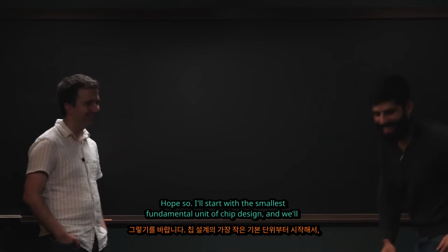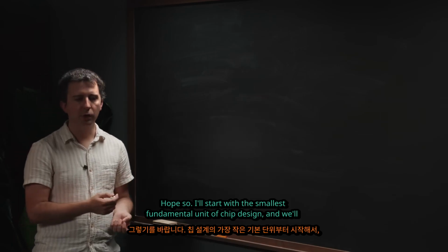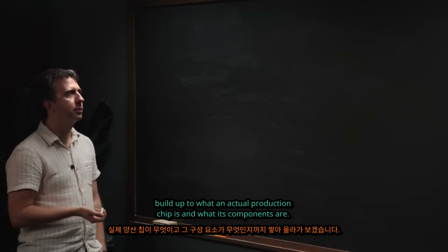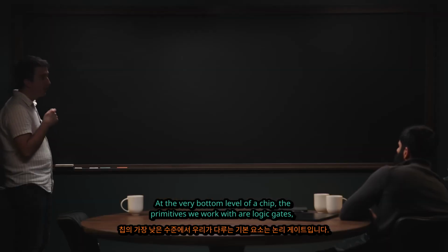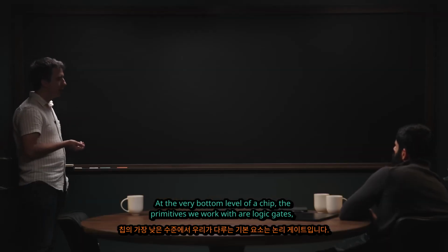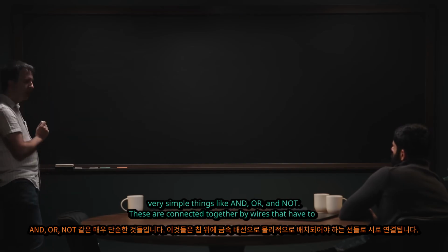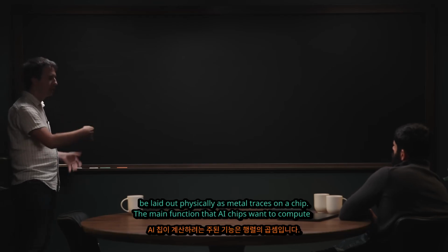Okay. So I'll start with the very smallest fundamental unit of chip design, then we'll build up into what the components of an actual production chip are. At the very bottom level of a chip, the primitives that we work with are logic gates, which are very simple things like AND, OR, NOT. And then these are connected together by wires that have to be laid out physically as metal traces on a chip.